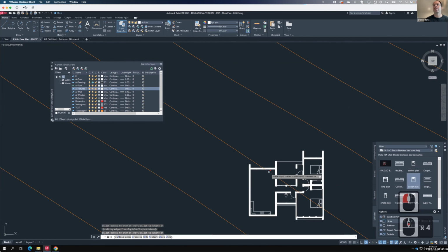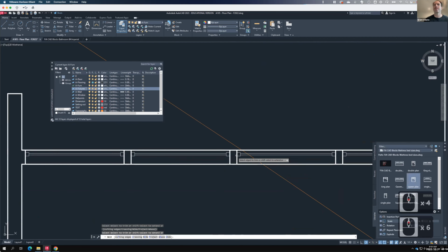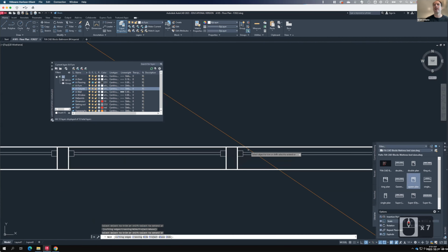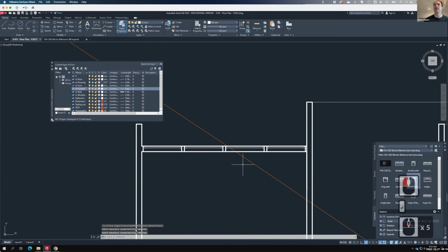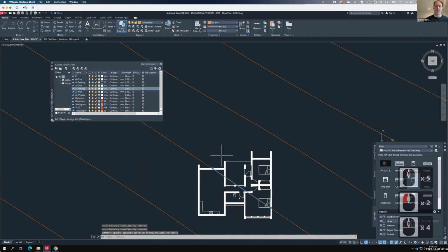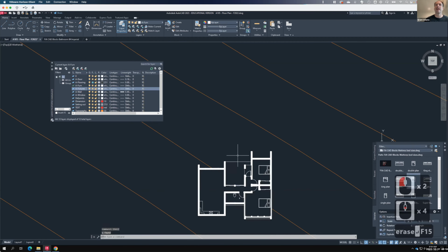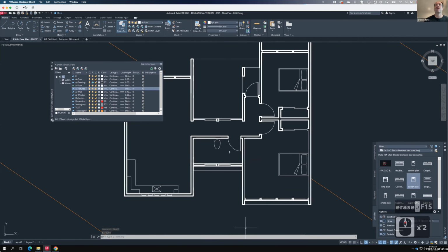And I'll come back to here and I will trim it right there. I'll hit enter or return to finish. And then I'll select the contour line and then we can just erase it. Press the delete key on the keyboard or type erase. And there we are. So now I would go ahead and make a JPEG of it.